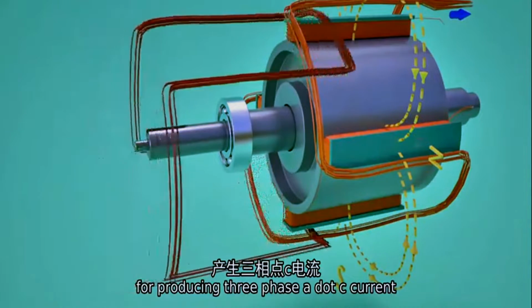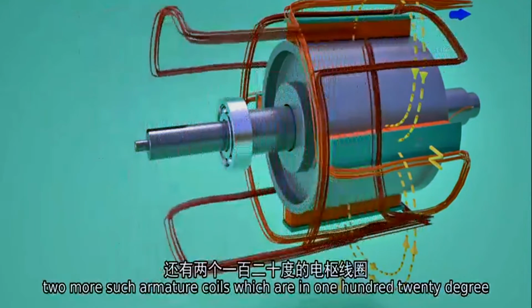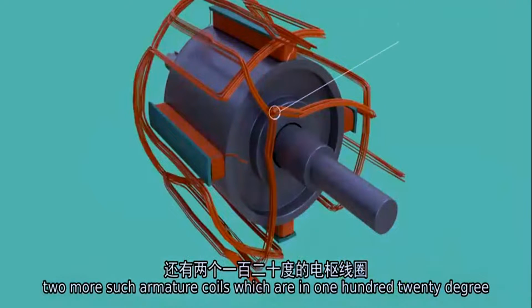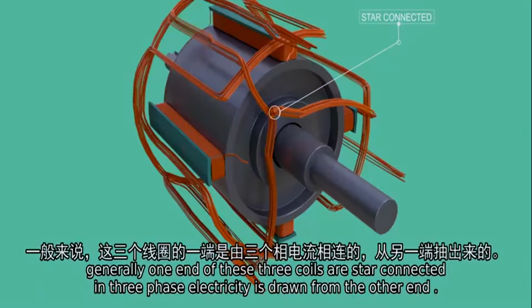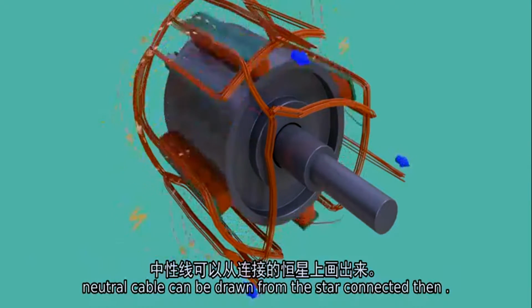For producing 3-phase A.C current, 2 more such armature coils which are in 120-degree phase difference with the first are put in the stator winding. Generally one end of these 3 coils are star connected and 3-phase electricity is drawn from the other ends. Neutral cable can be drawn from the star connected end.